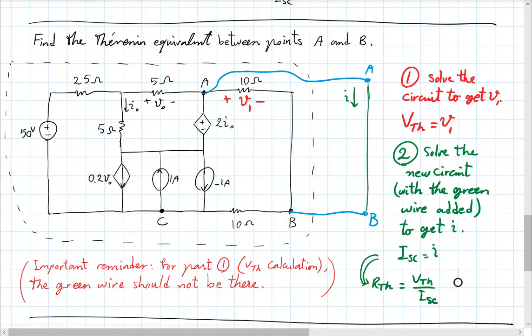And then to calculate the I-Thevenin for that, I would have to connect the wire between points A and C and solve that circuit, get the current going through that wire, which is again a different circuit. And that would have been my short circuit current. So in that case, I would have brought the wire out. Same circuit, but from a different point. And it would give you, in principle, an entirely different Thevenin voltage and an entirely different Thevenin resistance.